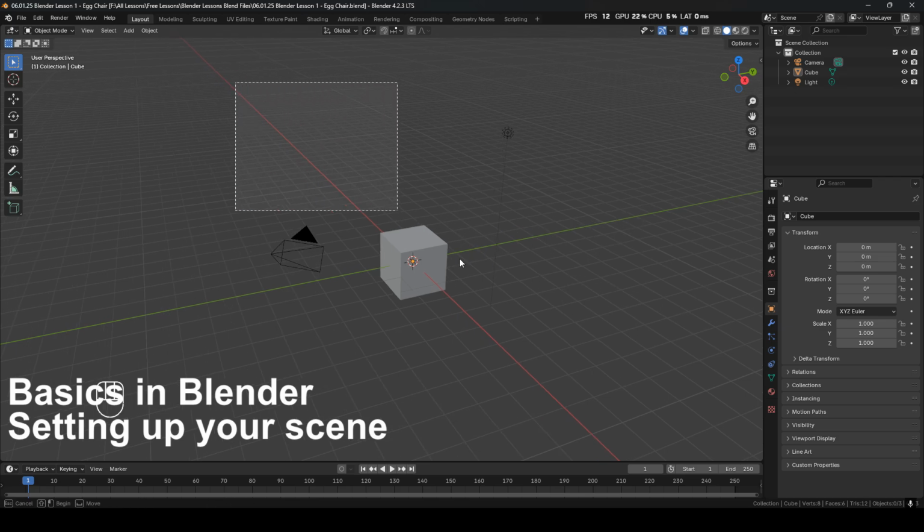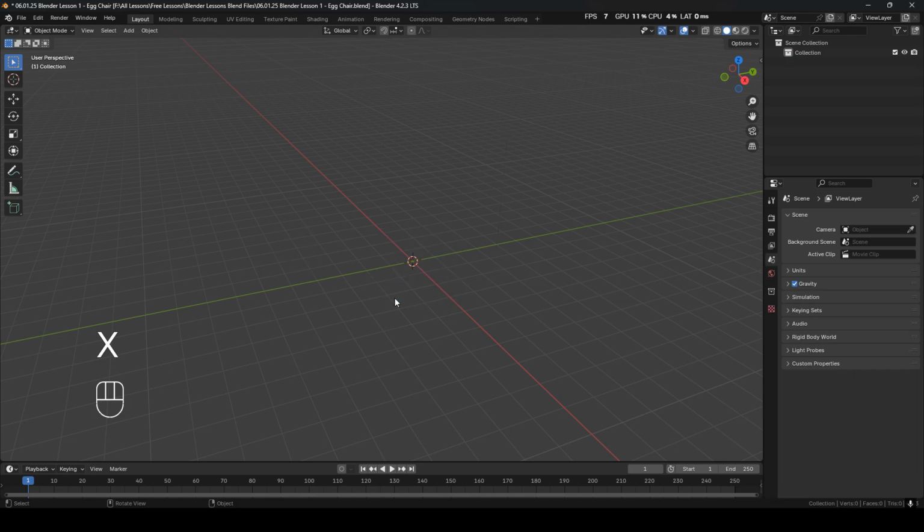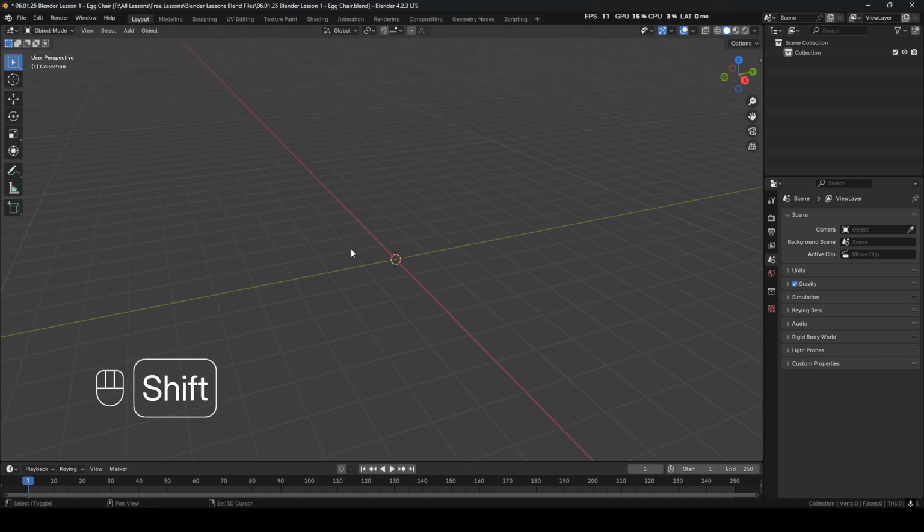We're going to left mouse button and drag, and we're going to delete everything here. So you press A to select everything, or just click and drag over everything you see. We're going to press X and then press delete, or you can press delete on the keyboard. But I prefer to use X because we will be using this in our workflow as we go along.